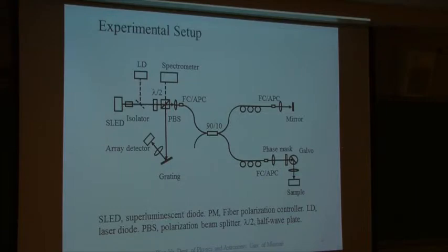You can also use a femtosecond laser, but it's more expensive. A SLED is a lower price semiconductor technology. This is a high gain, single pass broadband light source with very good spatial coherence and good shape of light coming out from there. And then you have a microscopy interferometer, just two-beam interference, reference and signal.